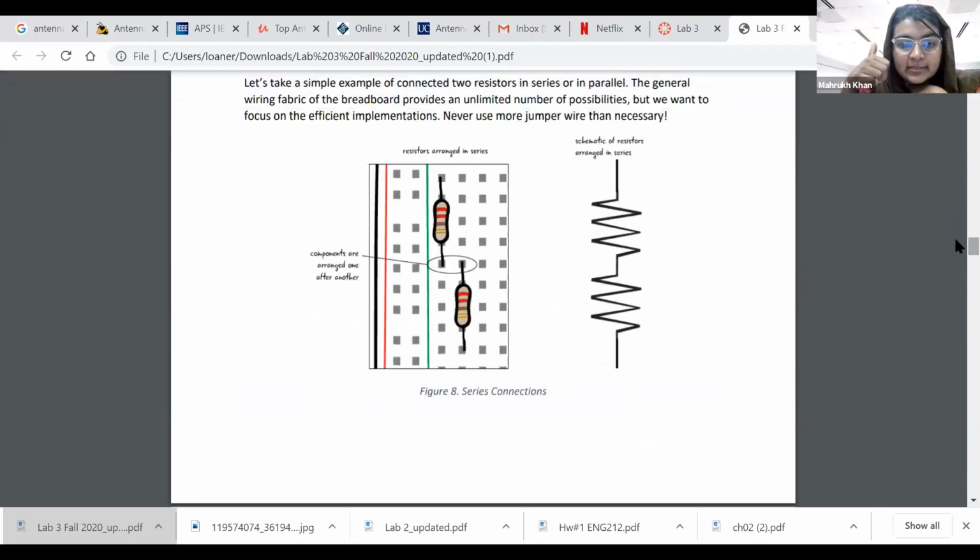One is with 3 volts, 1 resistor with 3 volts, voltage measurement. Then there is current measurement with 3 volts. Then there is voltage measurement with 12 volts. And then there is voltage measurement with 12 volts. But for you to do in the exercise, with the same circuit, you may have to change the resistor value, like the 10K resistor, you need to put it in. And the other thing you may have to do is just take the 3 volts out and try 9 volts as you were trying 3 volts.